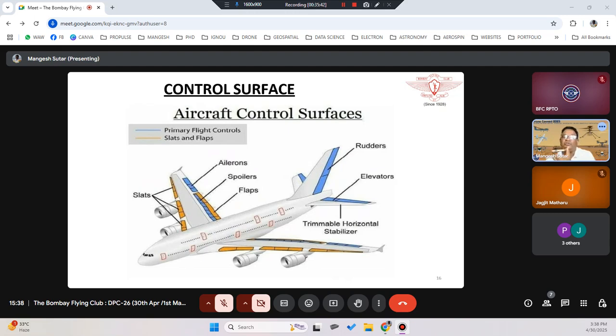It is moving away from the position, going forward away from you. You are the pilot in command, and you are outside. So when you are flying, when the drone is moving away from you, it is called pitch forward. When it is coming towards you, it is pitch back. Whereas this is roll right, this is roll left. If you are moving the drone in this direction, you are changing the heading. It is called yaw right. When it is moving to the left side, it is called yaw left. Understood how the four motions work?